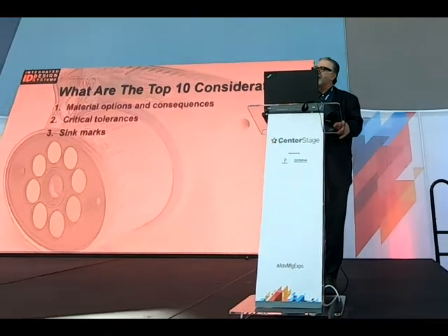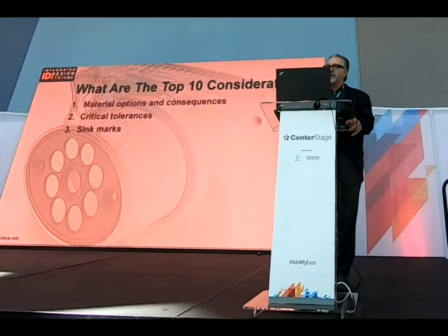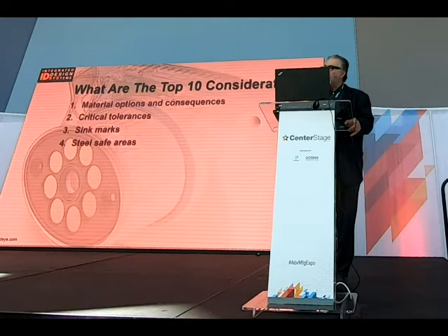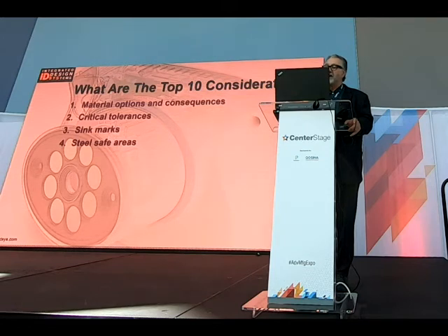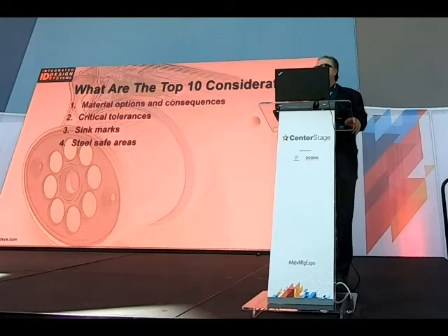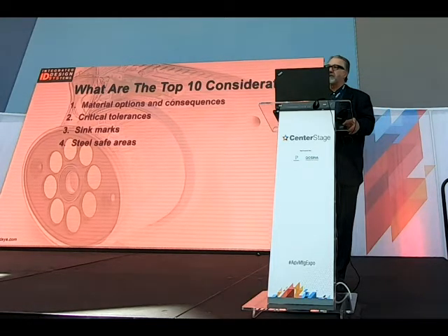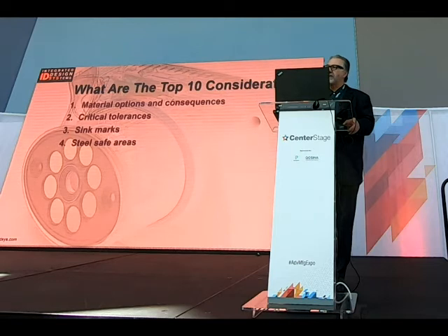Sink marks are an inherent property of injection molding and plastics because of the poor thermal conductivity, and we'll discuss that as well. Then there's designing parts with an understanding of tool design. The term steel safe means designing a part, especially with critical tolerances, sometimes with a looser fit so that adjustments have to be made in the tool instead of welding the mold to add material and then machining it. You basically leave extra steel in the tool. The part is basically shorter or smaller than it should be, and then you go back and modify it later after you get first samples.